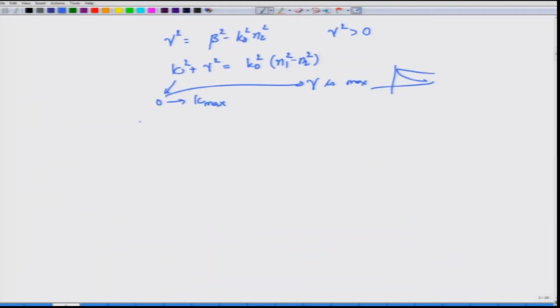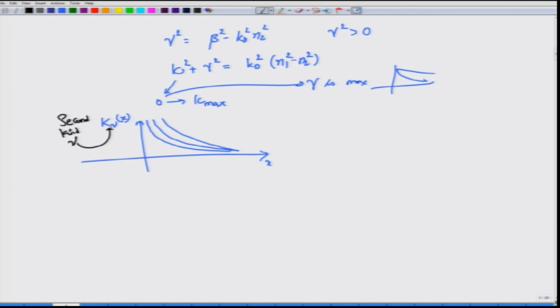The other Bessel functions, which will be the solutions outside the cladding, which you want anyway because you are looking at evanescent waves, are called the Bessel functions of the second kind. These are the second kind and order nu. Again, the order is nu and I have used k to denote the second kind. Some authors use y, some authors use n. So, these are all different notations. Please do not worry about those.